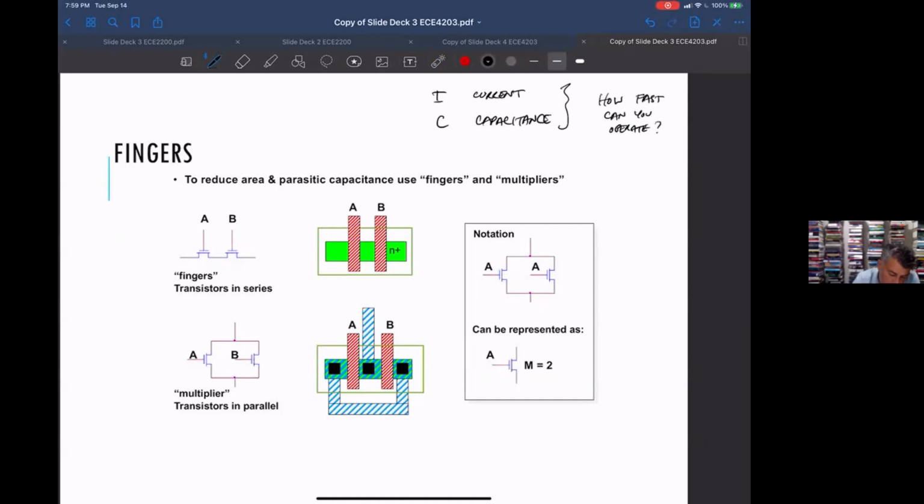The reason for that is, if you look at a very basic equation for charge and voltage, let's start with Q. Charge is capacitance times voltage. Somehow we want to get current out of this. Well, current is the change in charge for a given amount of time. So dQ/dt is C dV/dt. I'm just taking the derivative of both sides. So dQ/dt is just equal to current. That's the definition of current. So if I want to look at dV/dt, I'll get I over C.